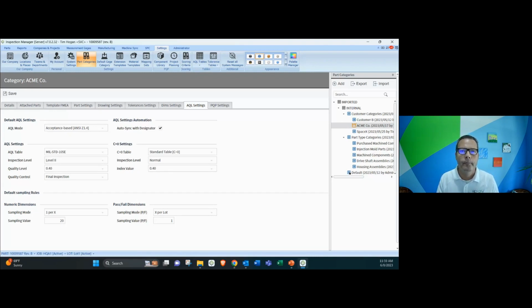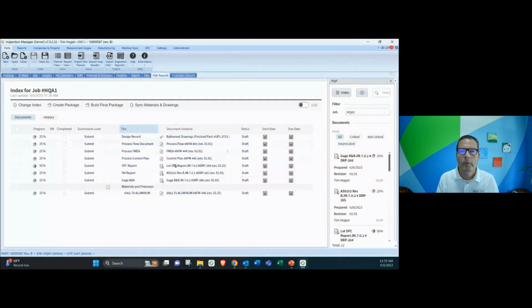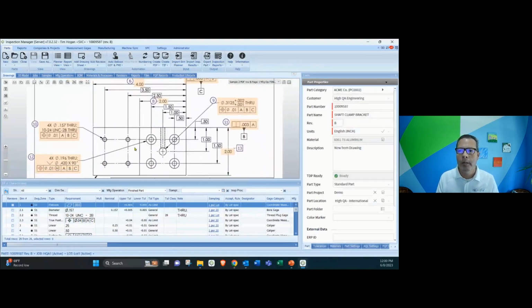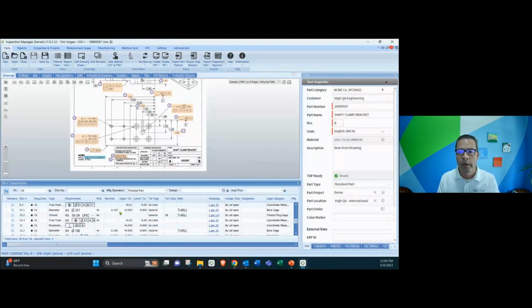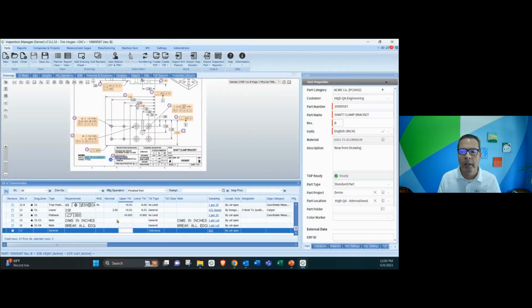This one is a bit technical. NDT information and instructions in the drawing. How do we get into the APQP and aerospace FAI? Example for radiography, UT, etc. in addition to CMM data? Okay. So it would need to be a requirement on the print. Now I say that loosely, and what I mean by that is you can add things to the print that are not on the print. Let me show you what I mean by that. So this is the same print we started with, right? Where we can come down here into the bill of characteristics and add a spec for NDT, non-destructive testing, if you'd like to, by simply clicking on add, and you can add any information in here.